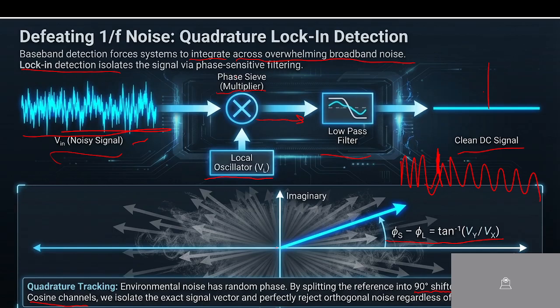This is your real part and this is your imaginary part. So you are detecting the in-phase component aligned with the reference, along with the 90-degree phase shift from the reference. It can be in the middle also, or at 90 degrees here, or at 30 degrees, 20 degrees, and so on.